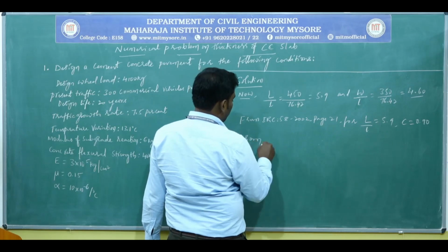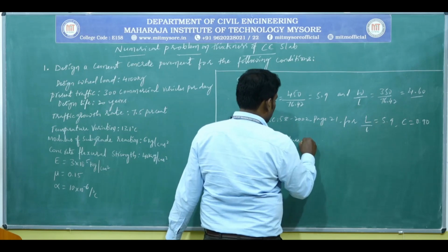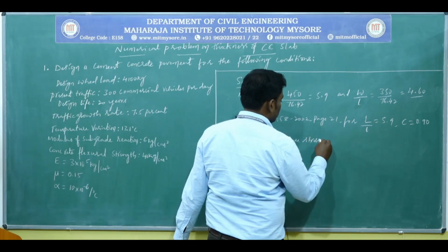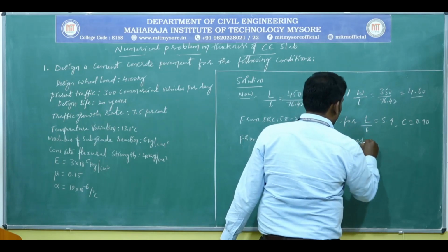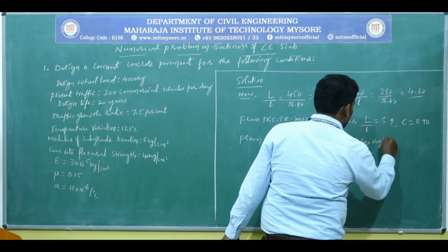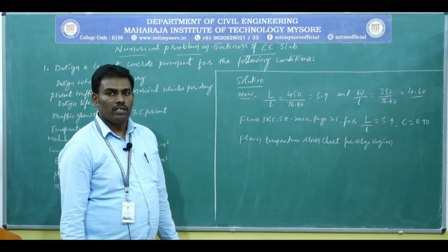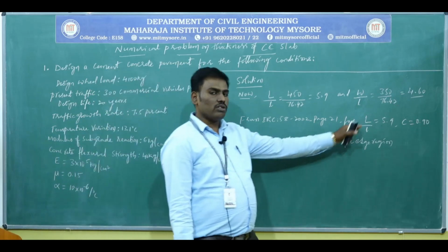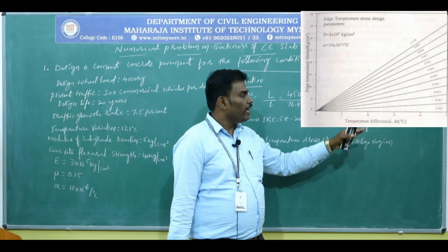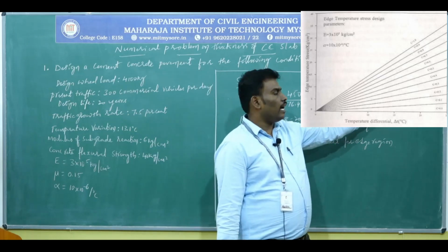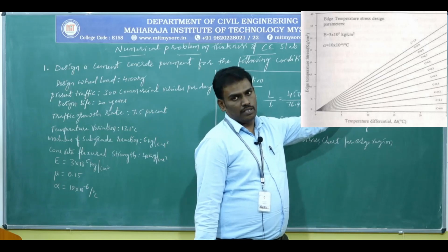Next, from the temperature stress chart for edge region, that is also there in your IRC 58 page number 21 only. You may see here, this is the temperature stress chart particularly for the edge region.